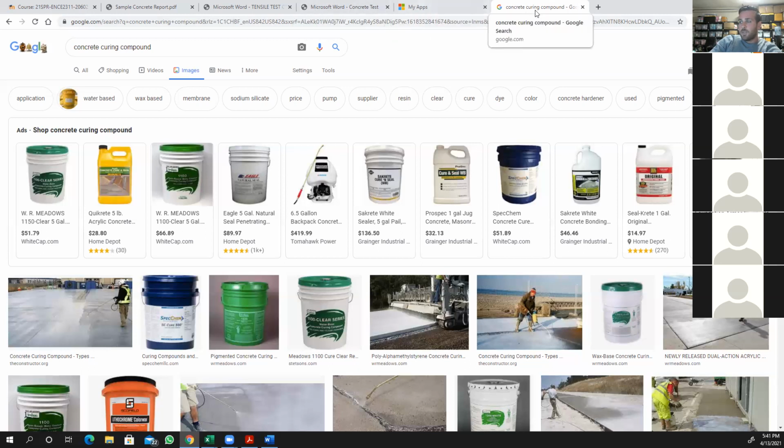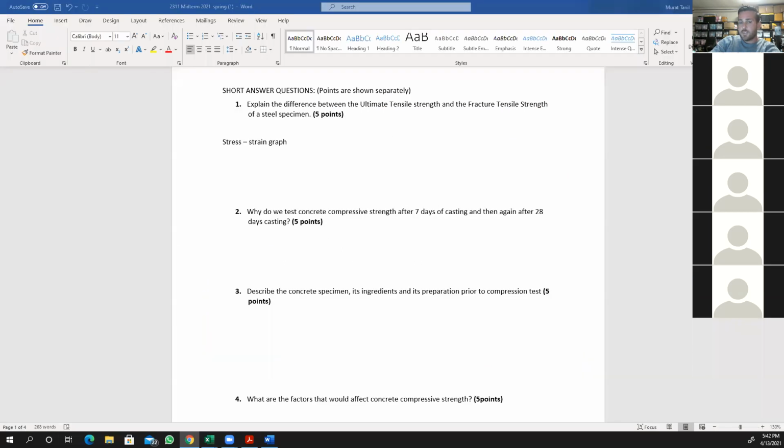postpone and prevent the failure, and it's the maintenance and getting samples from your structures. I don't know if you guys have ever seen or heard, you can even take core samples, cylinder core samples, like we tested our concrete cylinders. You can take the sample from existing structures, from a concrete column or concrete girder, and take it to the lab and see what the compressive strength of your member is during the service conditions. Is there any change? If so, what is the change? Or how you can prevent the failure, or how you can predict the failure. So these are the ways to go around it.